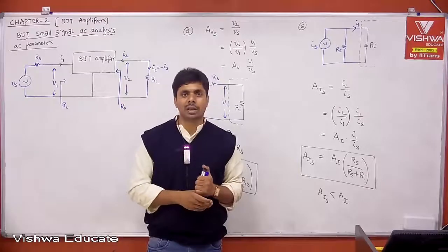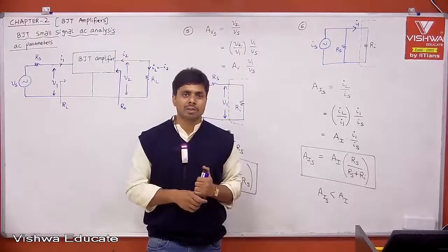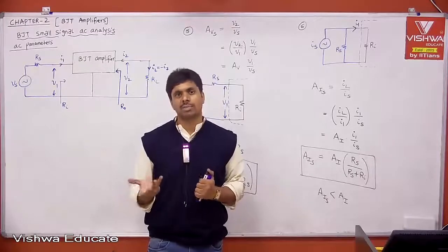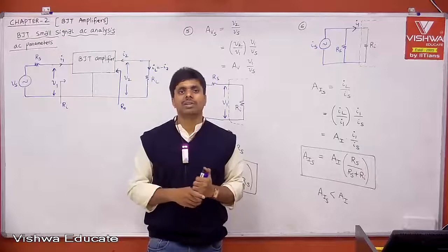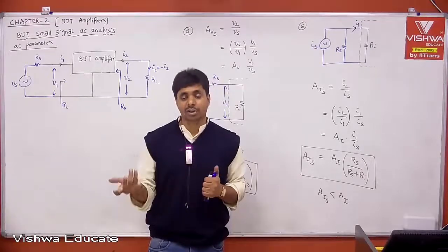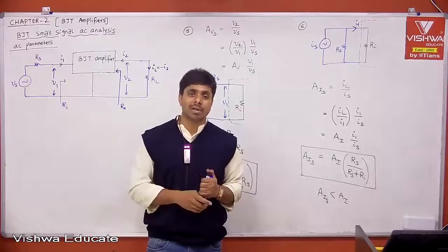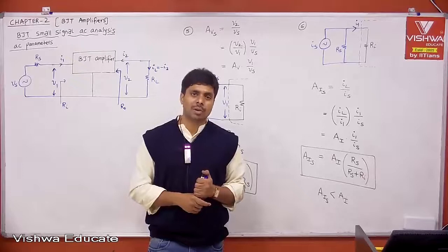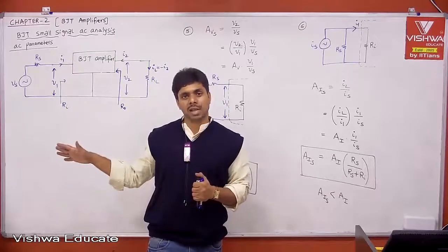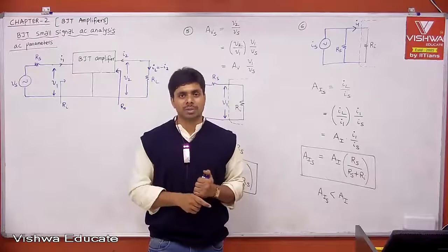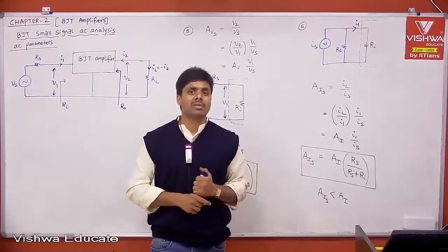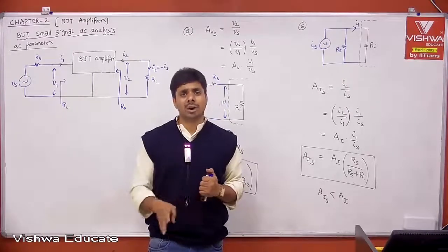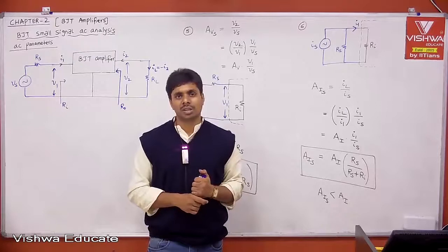We need not remember anything. And remember, those H parameter values are not constant. They are different for different transistors. H parameter values change with respect to different transistor configurations, and also with respect to temperature, doping, size, there are so many parameters. Therefore, we don't need to remember all those things. Whatever is given in the examination, use it and solve the problems. But let me give you typical values for the BC107 transistor. Then let's continue solving our workbook problems.